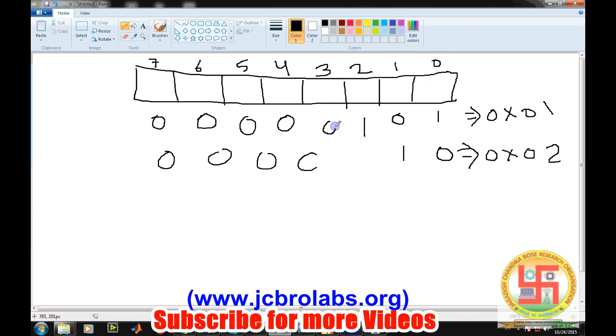So now there could be a total of 4 combinations for these DC motors, for motor 1 and motor 2. If both motors are running in the forward direction, then it will become 0x05, and the opposite will be 0x0a. In this case both motors will run in the forward direction, and in the other case both motors will run in the opposite direction.